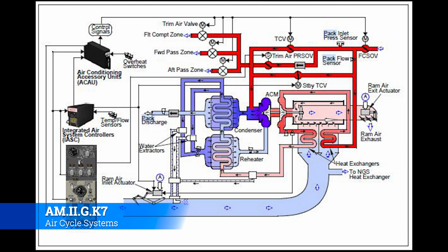But from what I've seen, and to be honest I have not really messed around with these that much, the problems that end up happening are usually stuck valves, broken motors or whatnot. That kind of basic thing. Not really super complicated to work on, but really important, because if you don't have a working pack, it's going to be bad for everybody involved, to include the black boxes in the E&E bay. You'll notice that the E&E bay has instrument cooling that comes up into it that's supplied by Pack 1, Pack 2.